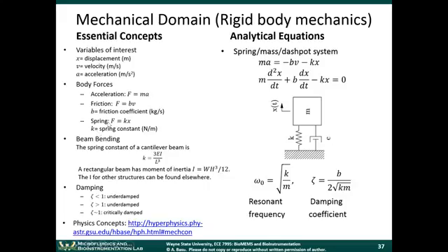So you have the mass here, and then you have this spring element, represented by K. That represents a force exerted on this mass that's pulling back on it. It's being accelerated in this direction, but the force is pulling back in the negative x direction. The third force is the friction force.